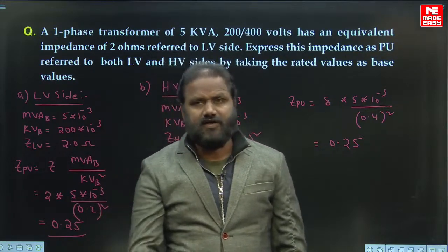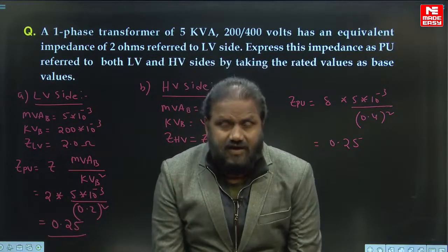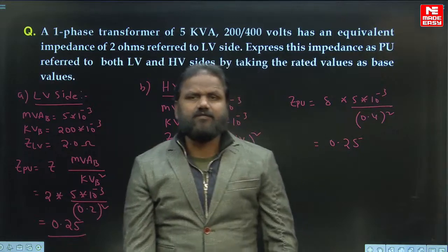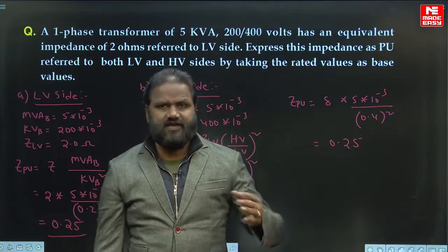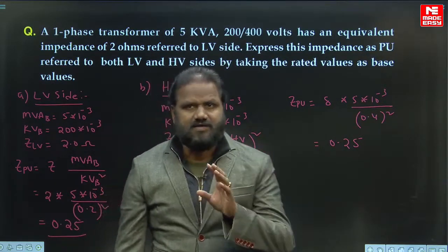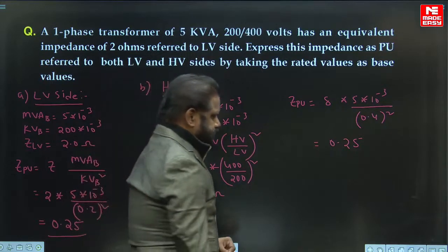One important thing that you have to notice is that the impedance in the transformer referred to the LV side or HV side, represented as a per unit, will be the same. There is no differentiation. Clear?